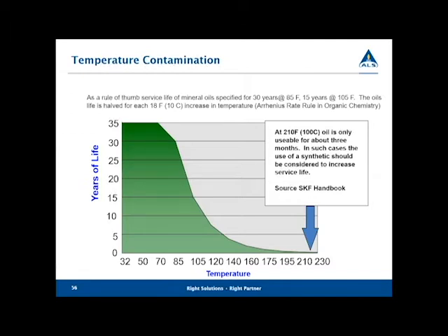If you can keep things cooler, the longer they're going to live. It's just the way it goes. That's why we stick things in refrigerators. That's exactly why we want temperature control and thermal management on all our lubricated systems. If we can keep the temperature in check, we can reduce the reactivity of particular types of radicals that establish themselves over time. If we increase the temperature, increase the water, increase copper, we're going to break down the oil. We're going to lead to a particular failure mode associated with a lubricated system.